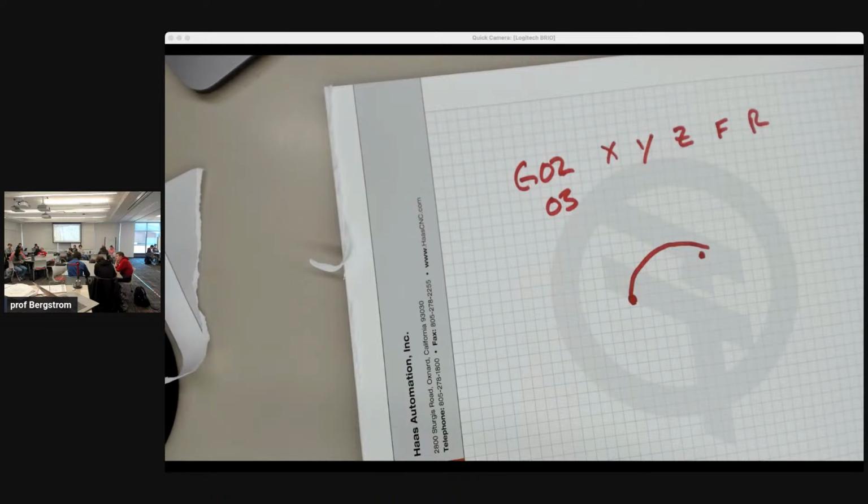The post processor is sort of this software that translates from what the CAM software knows to what the machine tool knows. The post processor is usually created by the people that make the CAM software. Sometimes it's created by some independent people. So I once downloaded a post processor that said that it was created for my Haas lathe. And it was really nice that the Haas lathe had 30 horsepower, because we made 4 parts before we figured out what the problem was. And the problem was that we were not making chips.